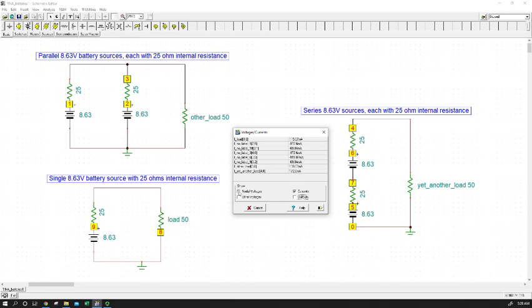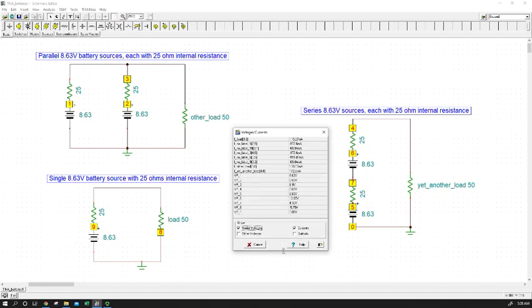And if you are displaying node voltages, as I just did, giving a little TINA preview, these are the voltages versus ground, versus wherever you put your little ground in each of these circuits, and the program's named them consecutively for all the different circuits that you use, so you could find that for everything if you wanted.